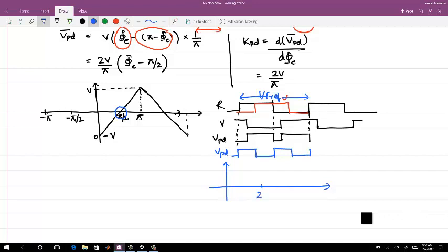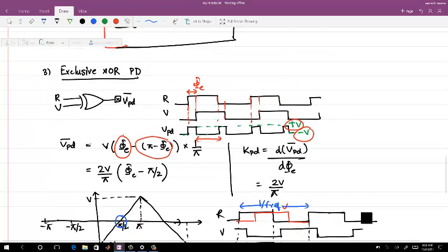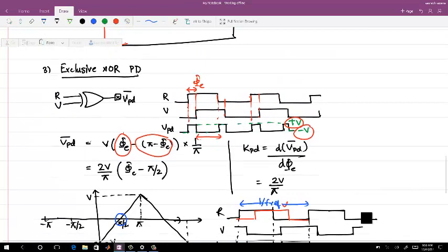So I will have 2 f ref and then the harmonics of that. Now these 2 f ref harmonics should be beyond the loop bandwidth. Otherwise you will see spurs with respect to this. There is another kind of phase error detector where the harmonics are inside. Interestingly, this is a digital block, which is supposedly non-linear, and it gives you a linear characteristic.